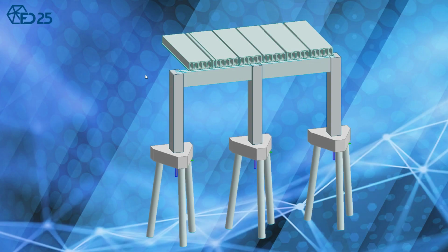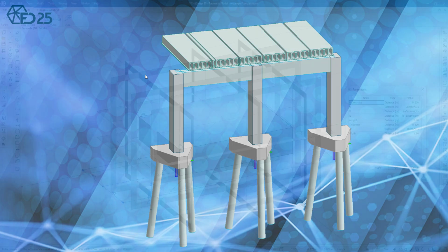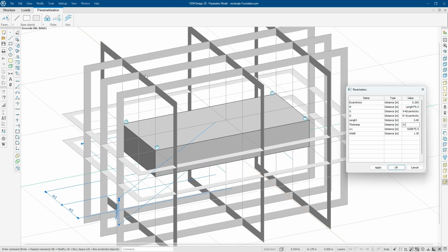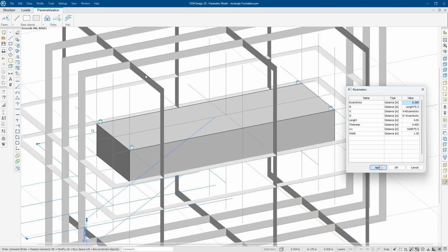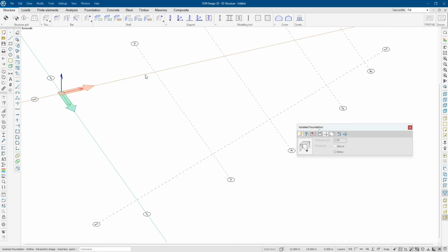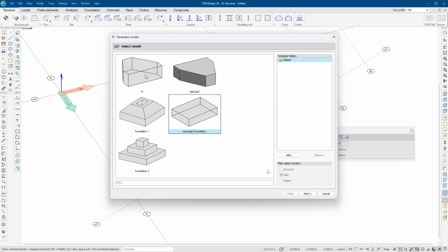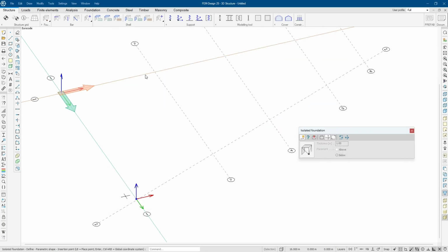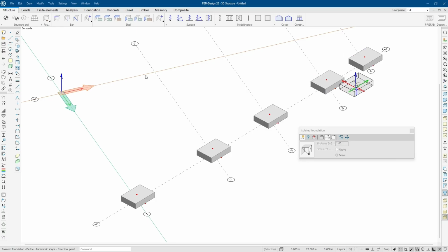Then you later add piles, or then you can make a volumetric or 3D block to also include the piles in the model. And also like isolated foundations, if you have rectangular, even that one is worthwhile to do a parametric model of, because now it's really fast to draw those isolated foundations with the rectangular. So like this one, or we might have an eccentricity or not. Then you need another version without the eccentricity, but the basic idea is that you set the orientation and then you place as many as you want in the analysis model.